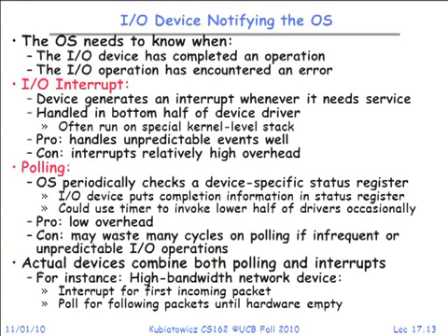So when you're polling, you're either doing an I/O instruction, an in instruction to the right port that's a status register in the device, or you've got a memory mapped status register and you're doing an uncached read from that address in the device. Either an I/O instruction, or a memory mapped I/O address, like we mentioned earlier.